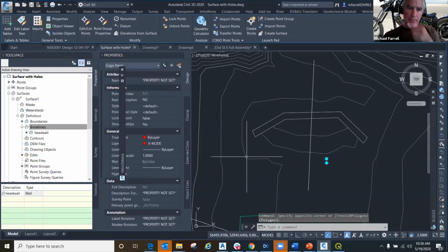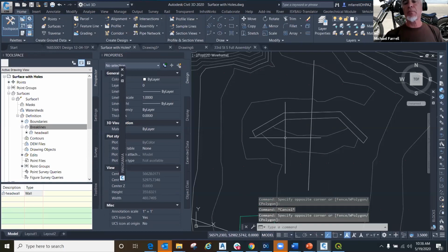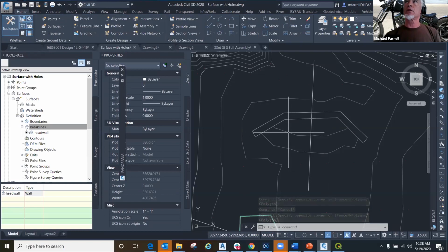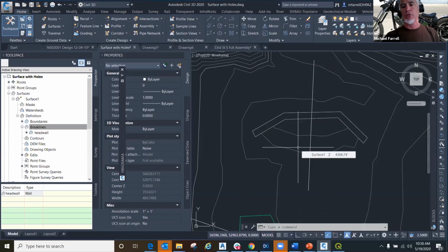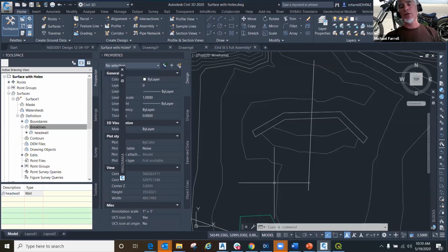Now, optionally, back to this surface with holes, sometimes those just come about naturally because you bring in the points, and if you recall, there's an option when you add points to the surface, whether you're going to minimize flat spaces, whether you're going to swap edges, there's those 3 options at the bottom. And those options can introduce those holes. Let me see if anybody sent me anything. Nope. Okay. Anyway, so those options can introduce those holes, as I alluded to.